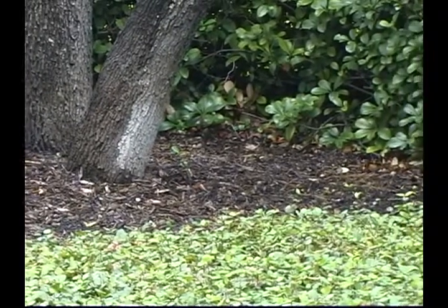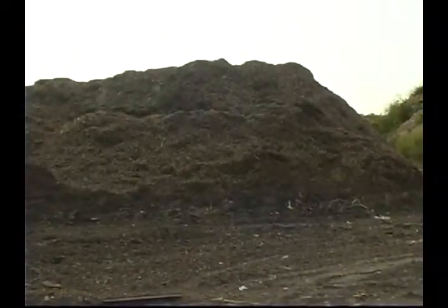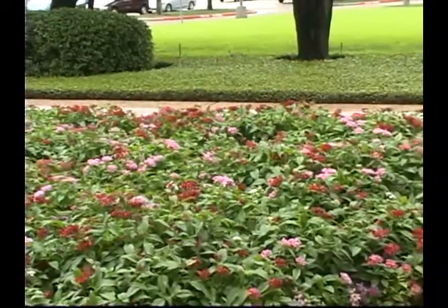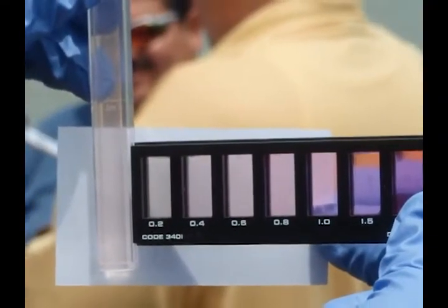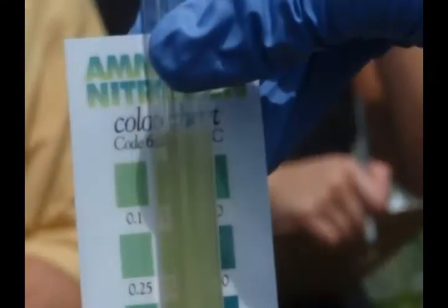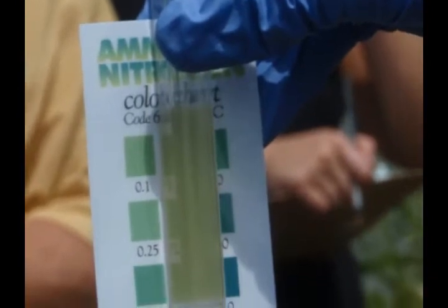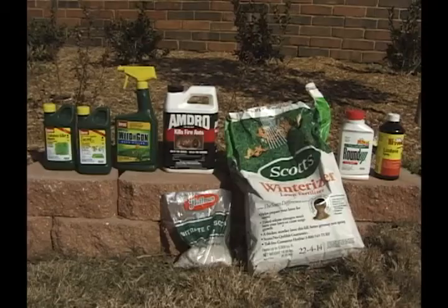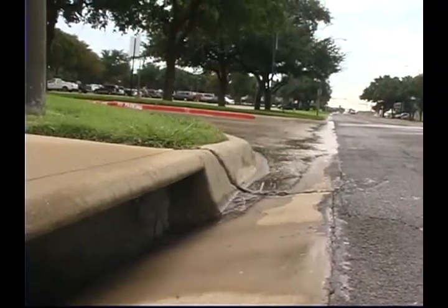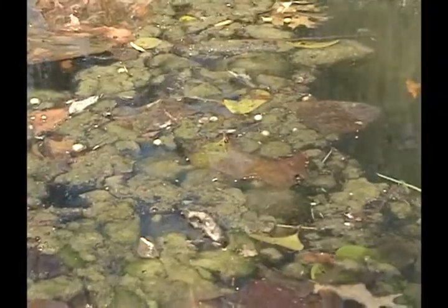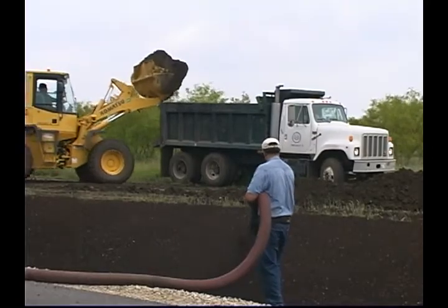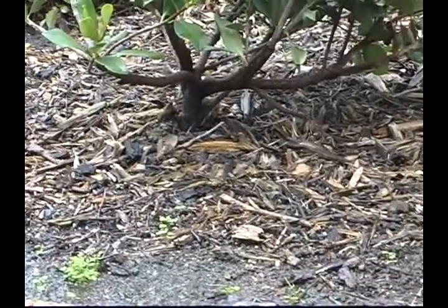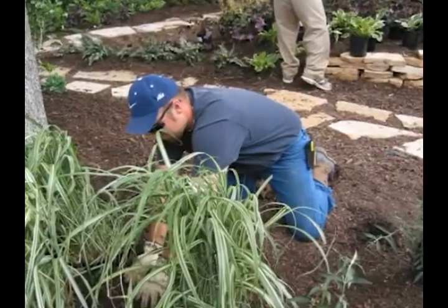Aerate and add compost to the soil to reduce fertilizer needs, improve drainage, and promote root growth. Have the soil composition tested well before the application season to determine fertilizer needs. This will help reduce the unnecessary use of fertilizer that could be washed into our waterways. Limit soil erosion by planting vegetation on bare areas and using mulch or matting for landscaped areas.